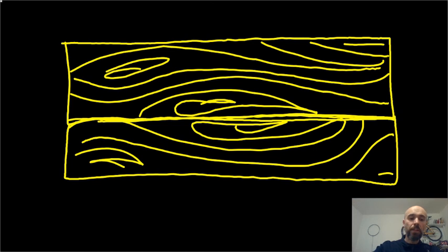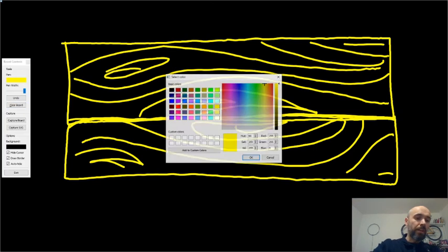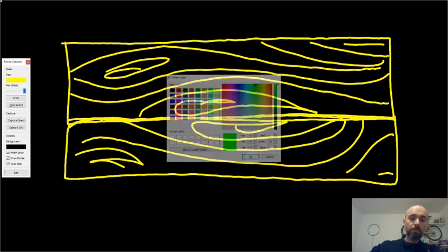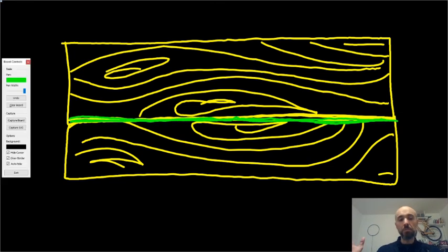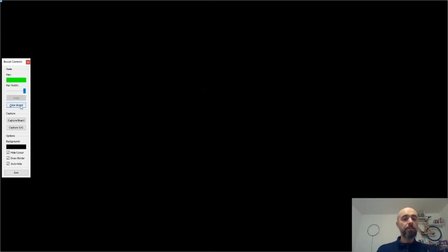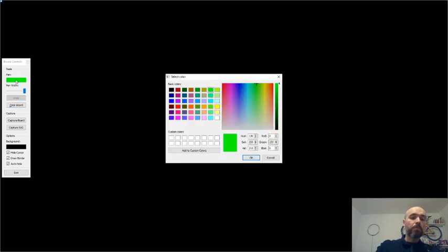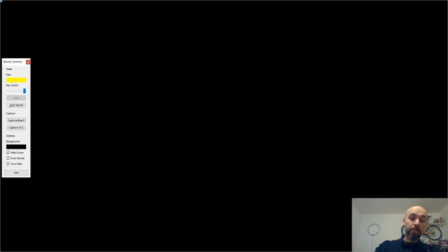So this connection here, if I glue the two surfaces along this line here, that should be working without any problems, without any particular treatments of the surface, because the fibers are parallel and the connection between parallel fibers is pretty resistant. That's not necessarily always the case. So it's actually not in the other direction.